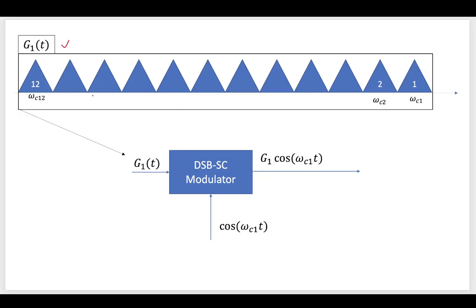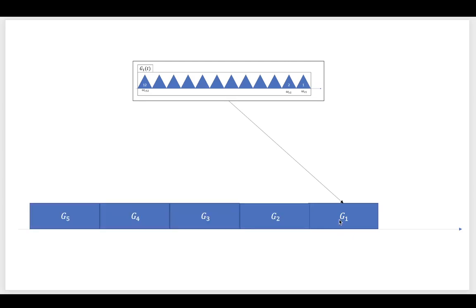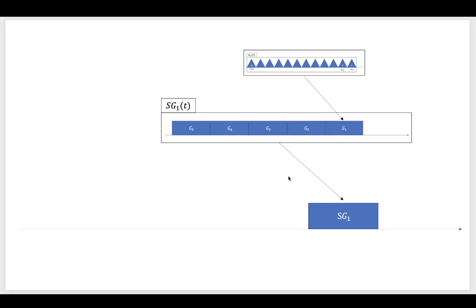And then you take that group 1 and you modulate the entire group. So you combine all these signals together and you modulate it with a new frequency or some other frequency. And then that whole group gets modulated out to that frequency. Then you can do the same thing for more and more of these. So this group could also contain 12 different channels that have been all modulated together. And you could keep going on this, right?